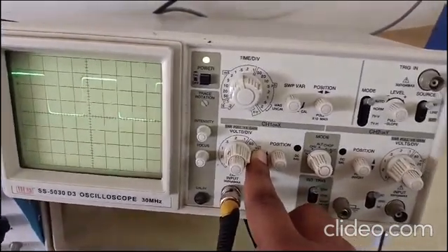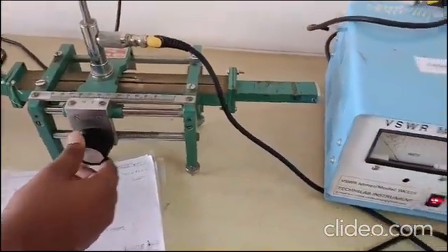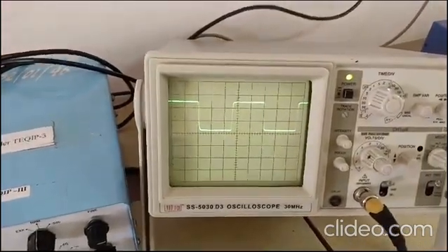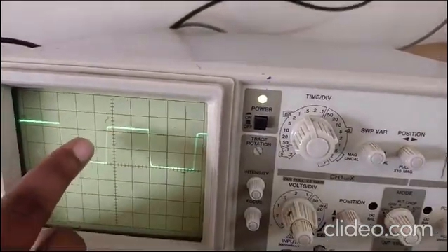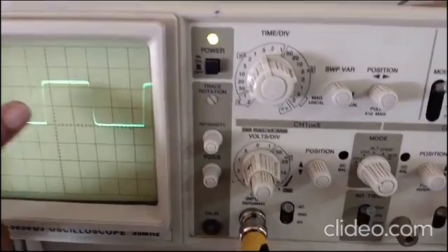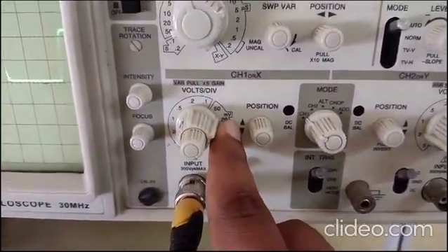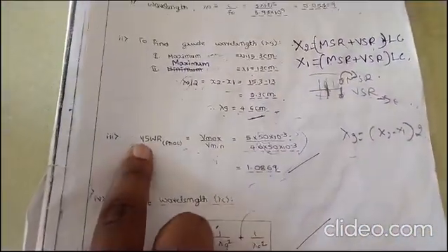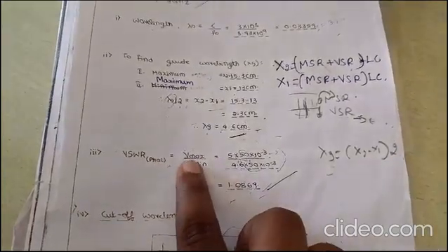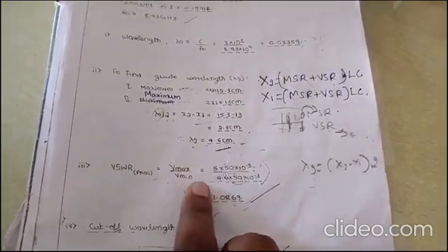Similarly, we have to find the V minimum by changing the slotted section here. See, just minimizing here. Now we can see it is near 2.2 to 2.1 multiplied by 20 millivolts to get the V minimum. Then you have to substitute the values into this formula to get the VSWR practical. That is how much you got for V maximum and how much you got for V minimum to get the